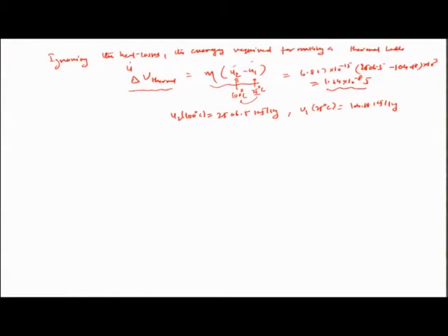So, let us look at that work done in this particular case. If I looked at both the cases, that is the thermal and the electrolytic case, the expansion work done by the bubble can be written again as the integral PdV, where P is really the pressure difference across which the bubble is expanding, and you know that that pressure difference delta P is already represented as a function of the bubble radius.